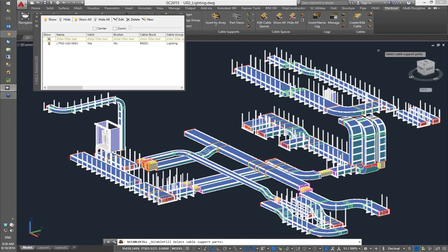The other thing is that the fill is actually monitored at supports. For the case of a hanger, it's fairly straightforward. What we do is we project the CG onto the center line of the space allocation, and that's the point at which we're going to check the fill. So any cables that leave or exit at that space allocation won't contribute to fill further on in that space allocation, but any cable that goes across that point on the space allocation we will track. So I can select a cable support.